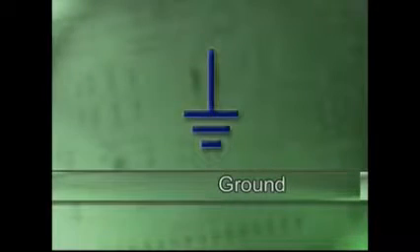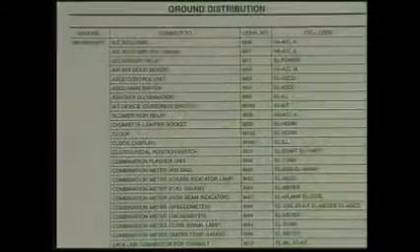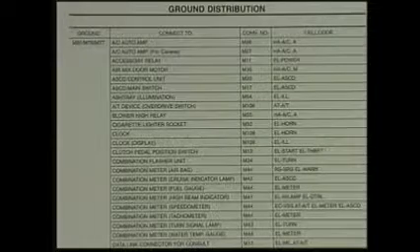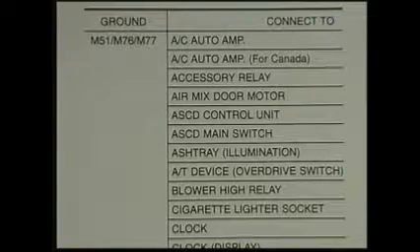All circuits need a ground to complete the circuit. In wiring diagrams, the ground is shown as an inverted letter T with two or more smaller lines under the bottom forming a loose triangle shape. As with connectors, many repair manuals have a page dedicated to showing the location of the grounds in the engine and body harnesses.